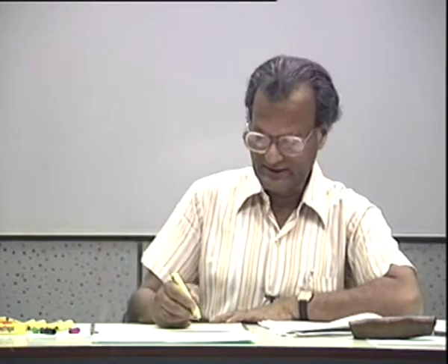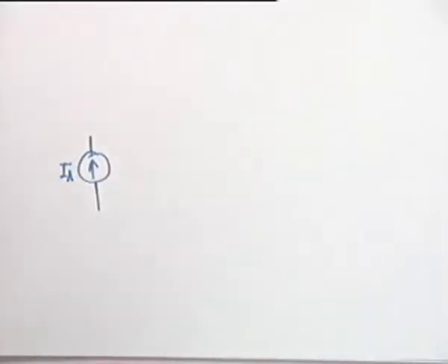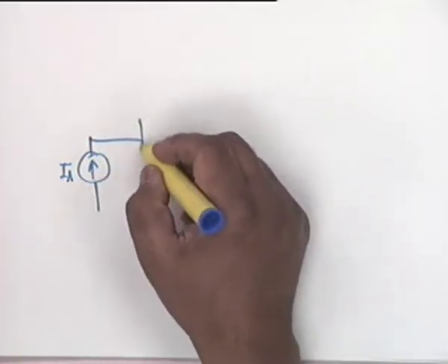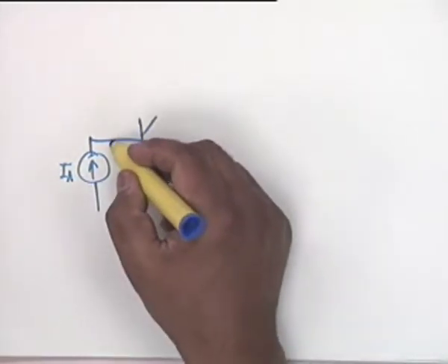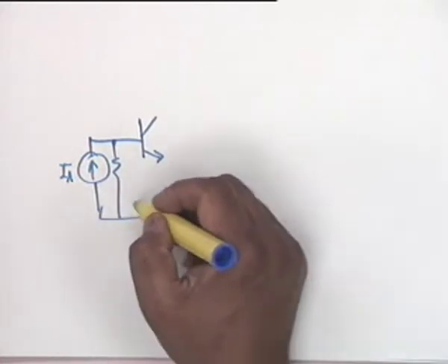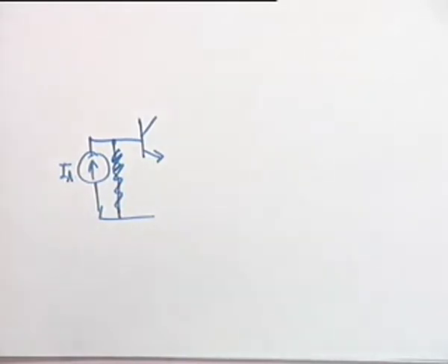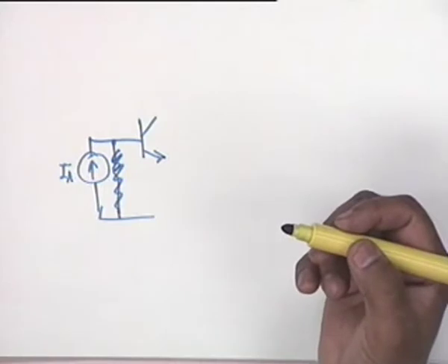On the other hand, if I do it the other way around, that is shunt, and that is followed by series, my circuit would be like this. Now, I must work with a current source because I have a shunt, and we may include an RS, we may not include an RS. All right, let's include an RS. Did we include an RS in the previous case? No. Then let's forget it. After all, that will come in parallel with R pi anyway.